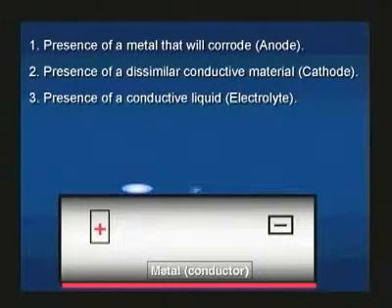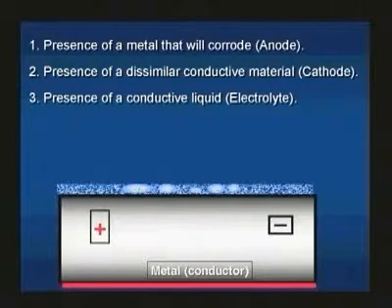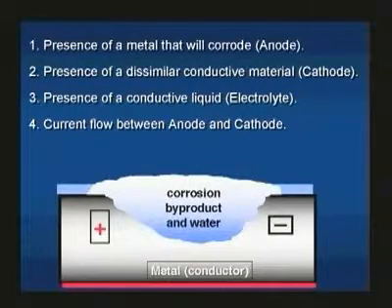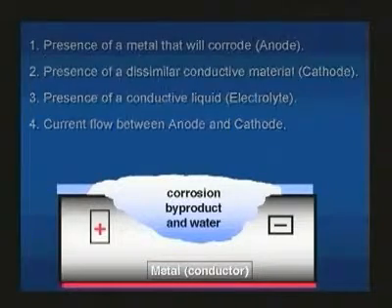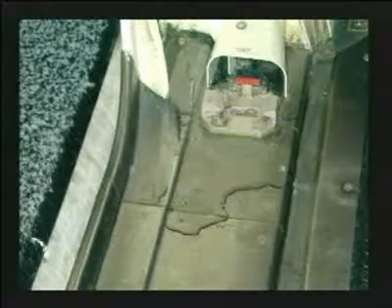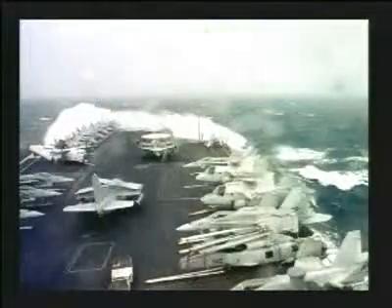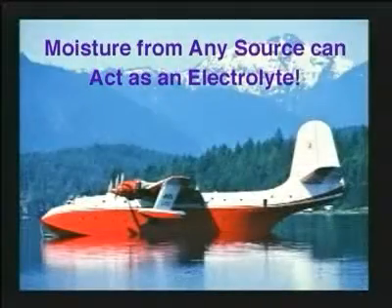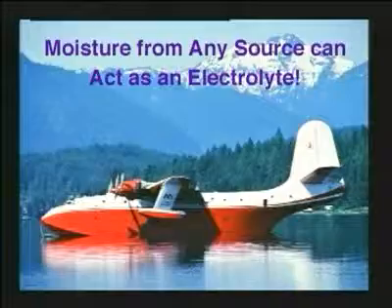When contaminated by a conductive liquid, which becomes an electrolyte, minute electrical currents start to flow. The corrosion process is like a battery, and it's this current flow, or electrolysis, that starts corrosion. Sources for these conductive liquids, or electrolytes, can originate as rain, humidity-induced condensation, soft drinks or juices, de-icing or toilet fluids, or even exhaust gas deposits that have been exposed to moisture.